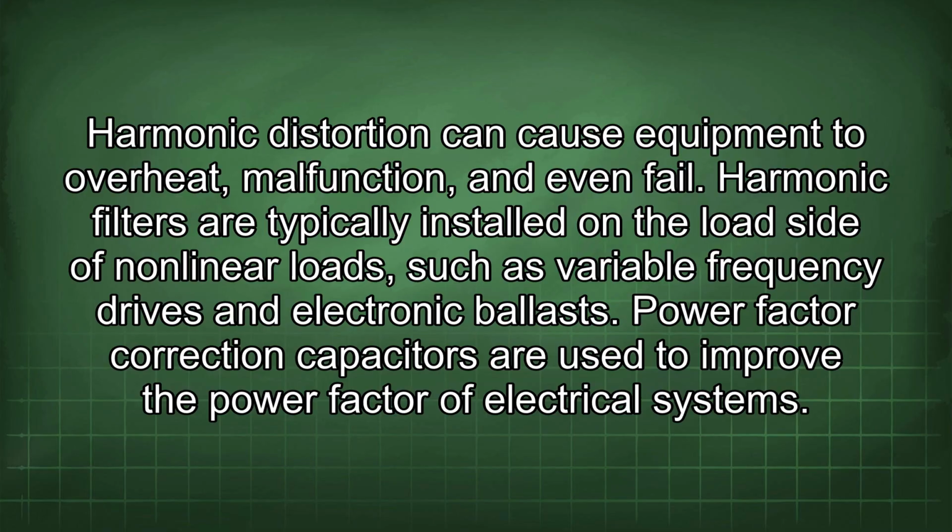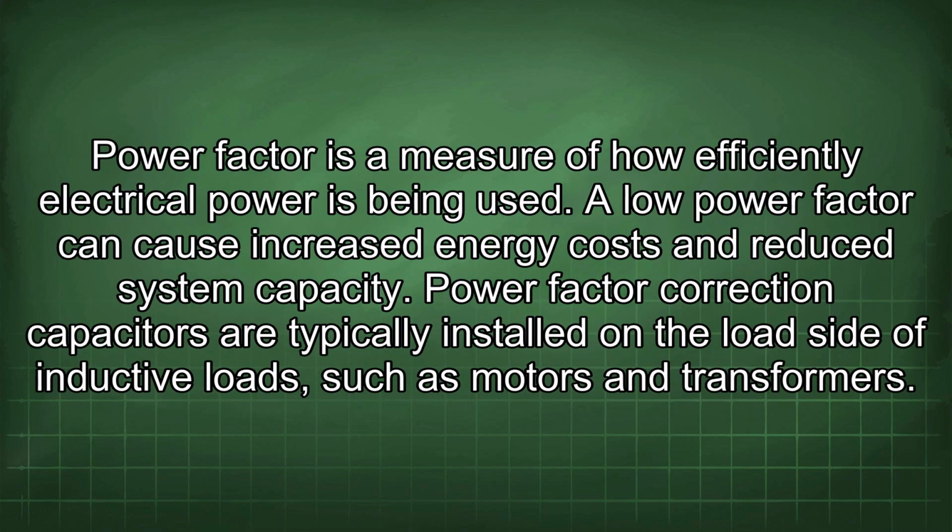Power factor correction capacitors are used to improve the power factor of electrical systems. Power factor is a measure of how efficiently electrical power is being used. A low power factor can cause increased energy costs and reduce system capacity. Power factor correction capacitors are typically installed on the load side of inductive loads, such as motors and transformers.